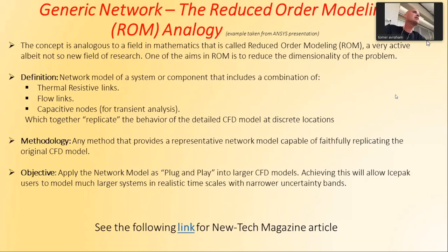So a little component, a little power here and there, and a little transformer here and there. You can use the Theta JB. Most of them are built such that they won't suffer too much. But the high dissipated components are even designed internally in such a way as to dissipate the heat. I mean, the FPGA you saw before, the Stratix 5, is a flip chip.